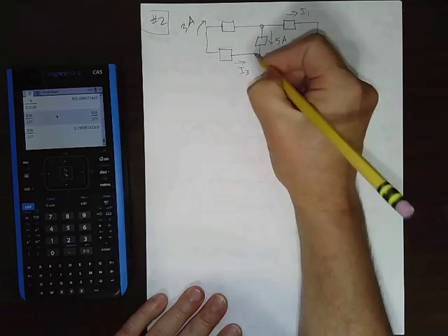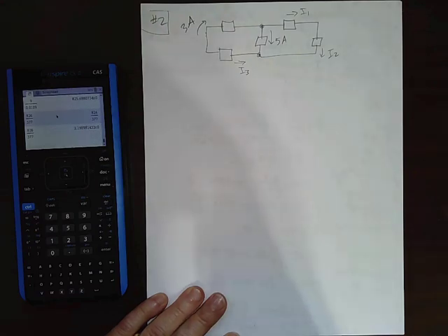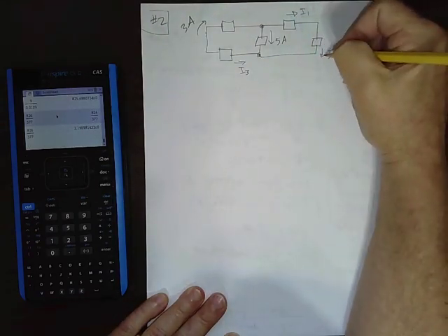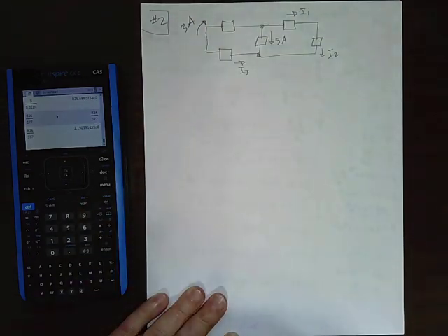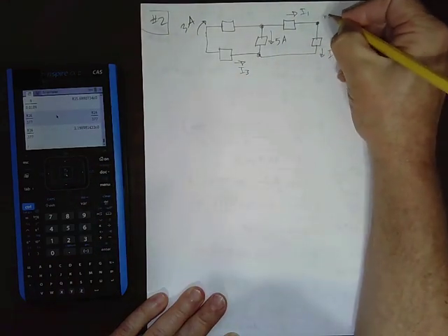Whenever you have a circuit like this and currents defined, or you're trying to define currents for yourself to start solving, which is a good step when you've got a circuit to solve, you need variables to work with, so you need to define your currents and possibly voltages. Let's look at this node to start with.